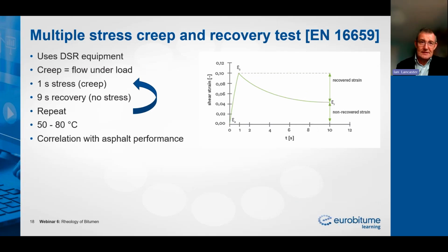One of our more recent tests that's been published is the multiple stress creep recovery test. This uses DSR equipment. Creep is a measure of flow under load, and creep measurements are designed to give you an evaluation of the behavior of a material under long-term loading.